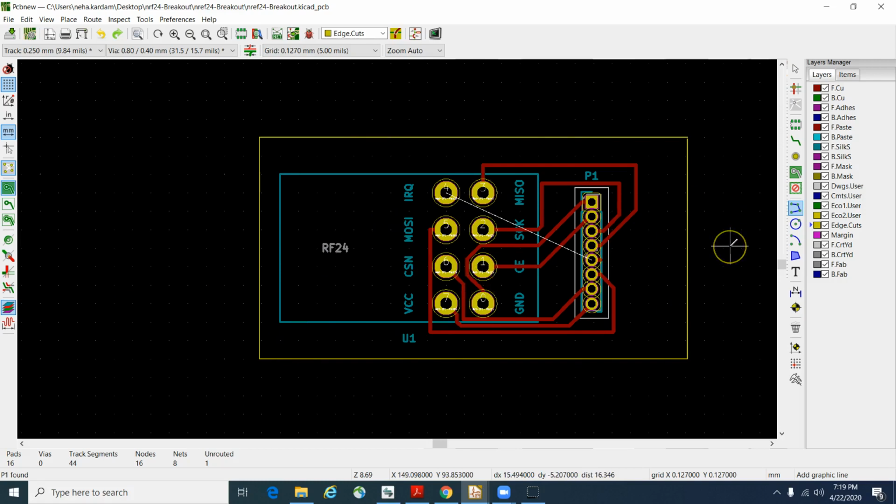Now I am going to teach you how to route between two pins on this schematic. To do that, you first need to click on the copper material. You will click here. You can see under layers there are many options, so we will choose the first option, this copper. Then the second step is to click on route tracks. I'm going to route between pin 4 and the connector.